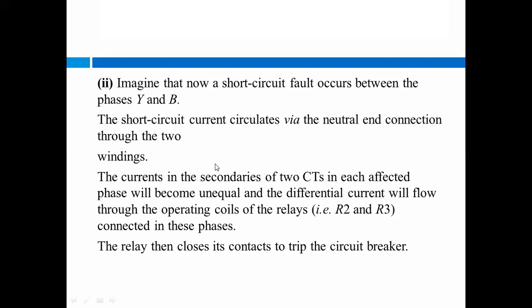The currents in the secondaries of the CTs in each affected phase will become unequal, and the differential current will flow through the operating coils of the relays.